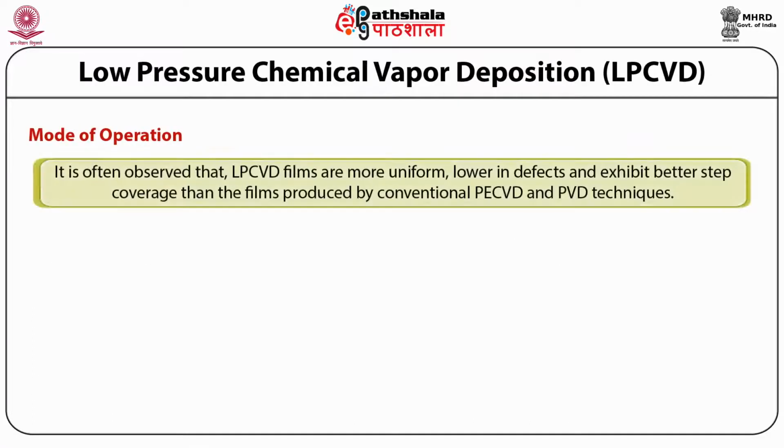Now, it has been observed that LPCVD films are more uniform, have lower defects and exhibit better step coverage than the films produced by conventional PECVD and PVD techniques.